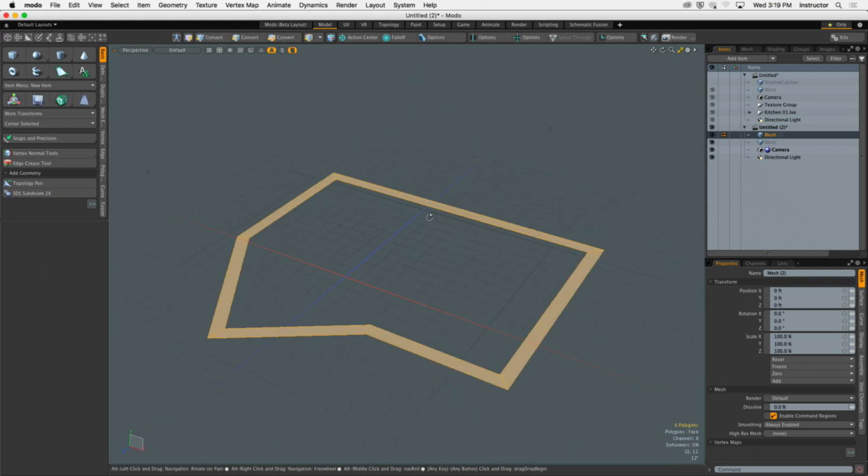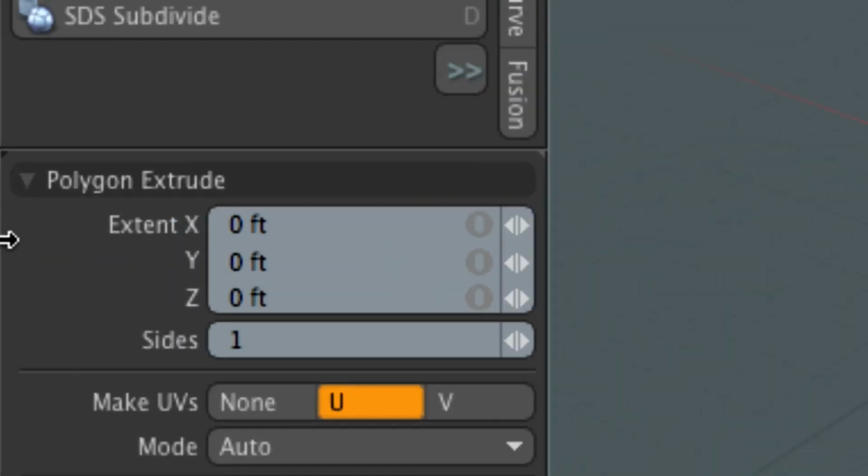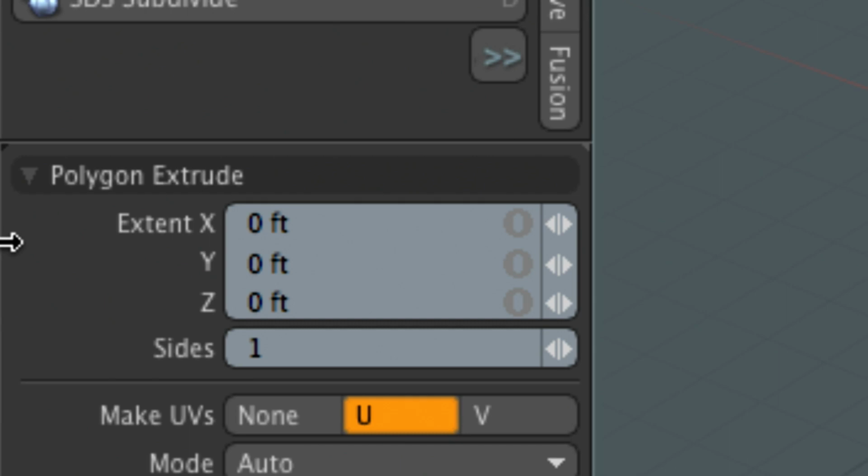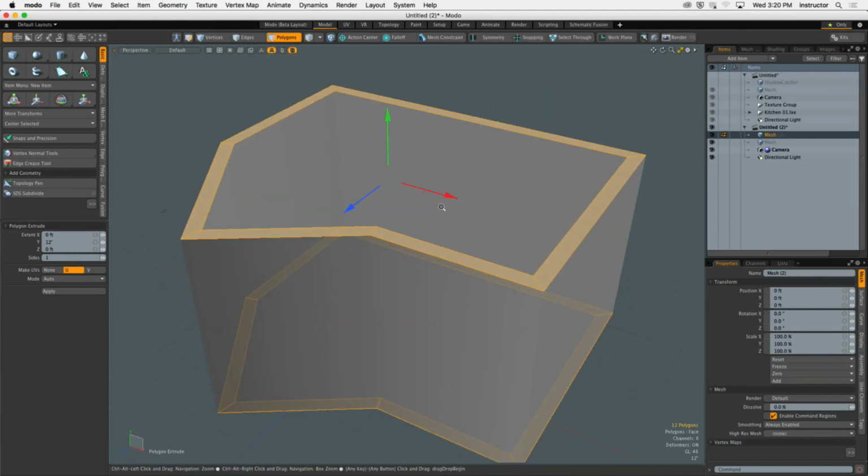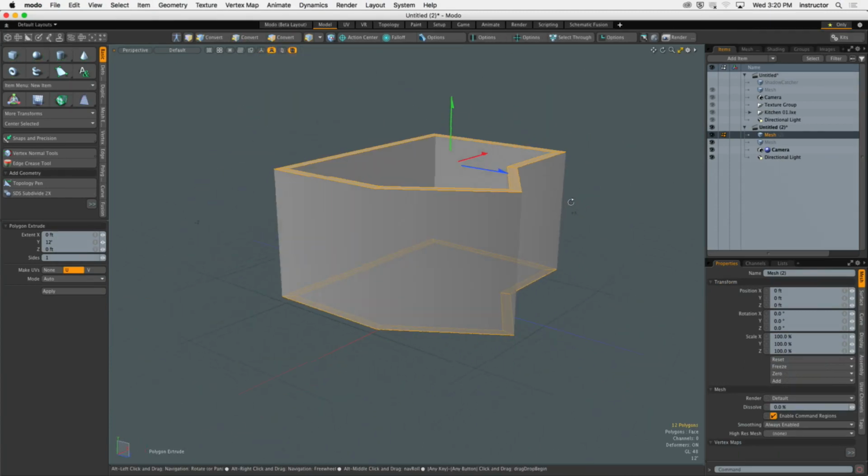The pen tool is always going to produce polygons for us. So how could I physically start to grow my walls from my simple little floor plan? Yeah, extrude's going to work, bevel's going to work, either six of one, half a dozen of another. If I run the extrude tool, check it out. Have you guys ever noticed that over inside of our tool properties, we have real dimensions in here? I could say I want my walls to be 12 feet high, right? Let's just do it real fast. 12 feet, hit the return key. Now I know with great accuracy that those are 12-foot high walls.